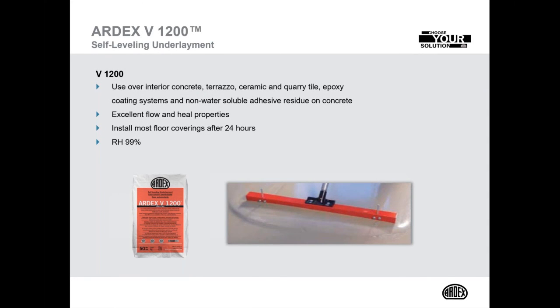Step down to V1200, that's our workhorse, concrete, terrazzo, non-porous surfaces, substrate, epoxy substrates. Great flow properties and heal properties with this material, most floorings in 24 hours. It's a lot more cost effective than K13, and that's why we consider it our workhorse. Does a majority of the work, the heavy lifting for us.